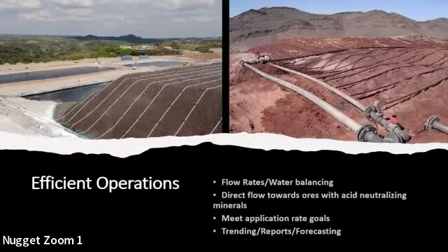So in conclusion, I think this work shows that a well-designed hydraulic property testing program can simulate conditions in an operational, large-scale heap, going from lab scale to large scale. The data can then be used to evaluate ore permeability for different ore types, the optimum heap height and irrigation rate to minimize the effects of consolidation, and the appropriate ore blending ratios to maintain permeability.